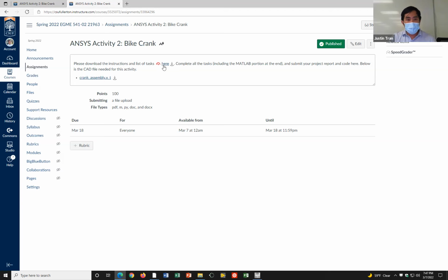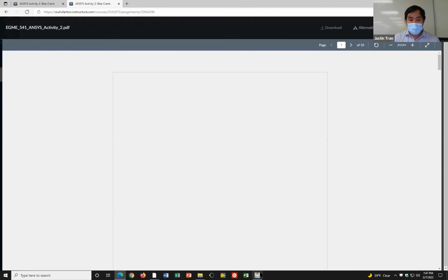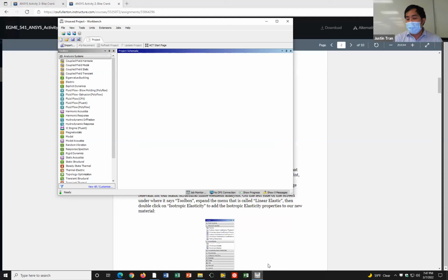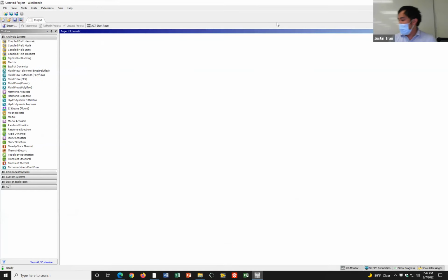Okay, and so with that, let's go ahead and come into Ansys. The first thing we're going to do is create a custom material property. All right, so let's go ahead and open up Ansys, and then we're going to start by creating a static structural simulation.